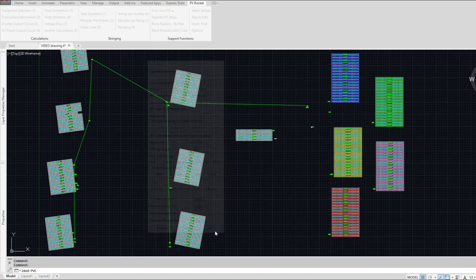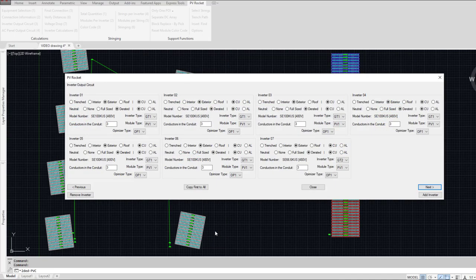There's also a thing called the rapid shutdown device that's coming up in popularity, because of the inner array rapid shutdown requirement, inside the array, not just within 10 feet outside the array. PV Rocket at this point doesn't even address those rapid shutdown devices at all, because it doesn't change anything on the calculations. Now, the power optimizer does. It actually does things slightly differently.